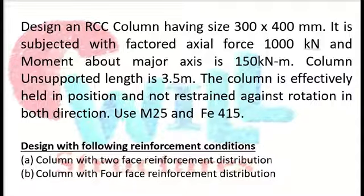Column is effectively held in position and not restrained against rotation in both directions. Use M25 and Fe 415. Here two conditions are given for the reinforcement in the column. One is a column with two-face reinforcement distribution and the second is a column with four-face reinforcement distribution.